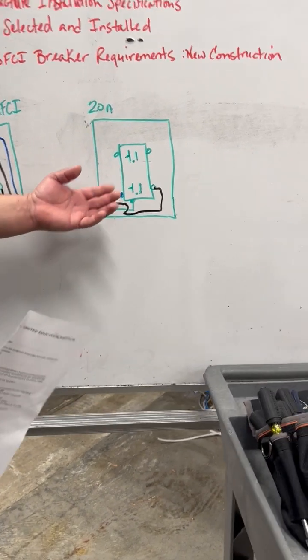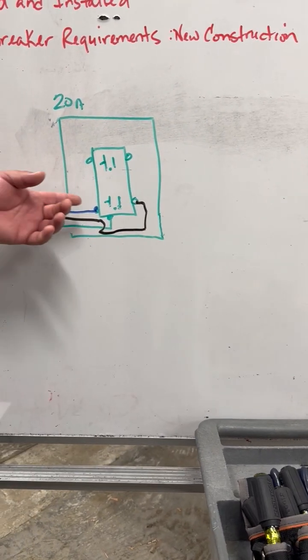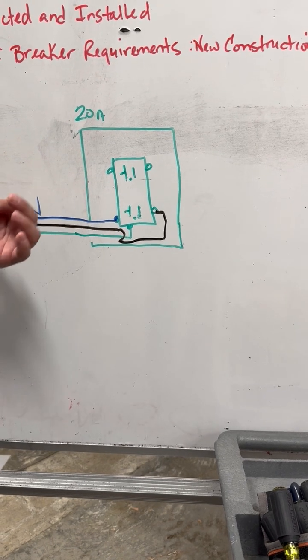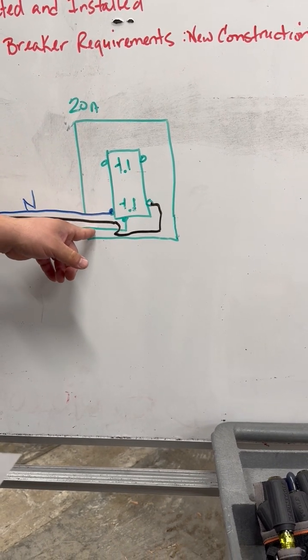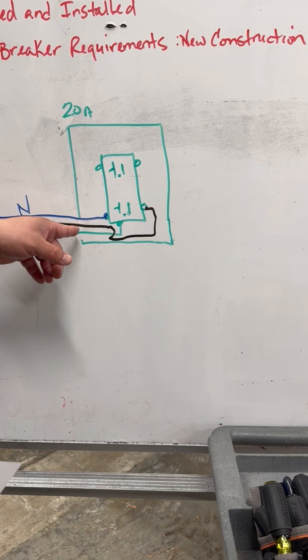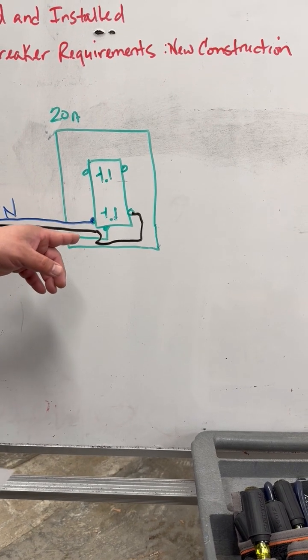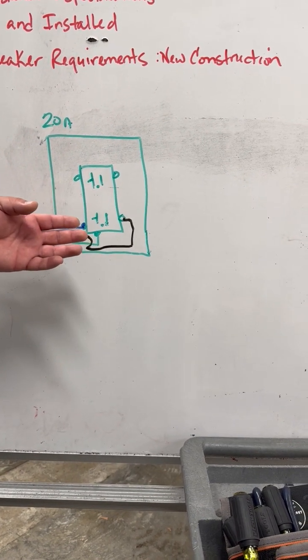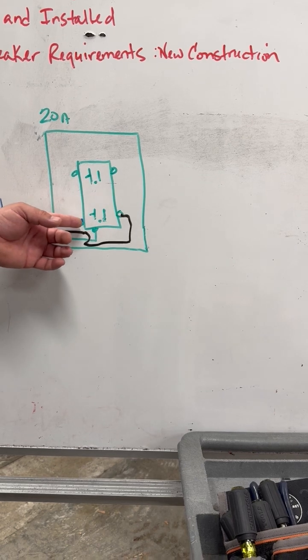As we come in, we follow that same format downstream. I know that my incoming power is coming from the left. I'm gonna have my grounding nipple closest again to that entry on the left side here for that knockout. And obviously we're terminating in this section. Again, I got my neutral coming in.